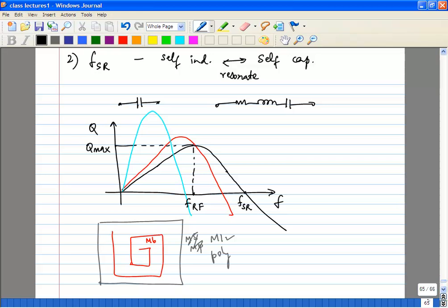The way these processes work is that any area outside metal is covered with oxide. The heights of the metals with respect to the substrate are constant. If you have M1, it is always at a certain height from the substrate, and between M1 and the substrate you have oxide. If you have M6, it's much higher than the substrate, and if you don't put any metal lines below it, there is just going to be oxide.